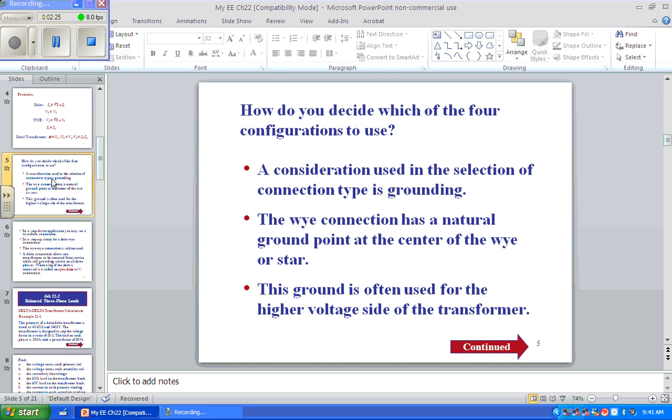All right? And I've talked before about some cities supply Y power, some cities supply delta power, or the utilities in those cities. Like the city of Los Angeles supplies a delta supply. It's ungrounded, and theoretically it has no potential to ground, but if you see one of those wires bouncing around on the earth, throwing arcs and sparks, you notice that it never ever disconnects because there's no path back to the transformer, so there's no way to trip the transformer unless it touches hot to hot. Unless there's a dead short, an ungrounded system will not turn itself off.